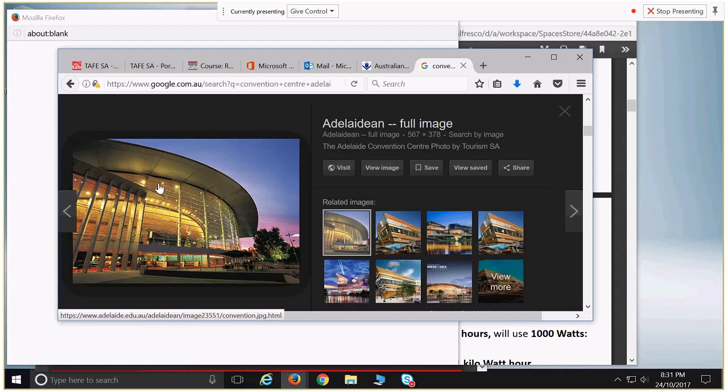So cable running up there, and cable running up there, and so in cross section, we've got our horizontal framing members and our glass coming off that, like that, and then cables with an adjustable nut, and then another horizontal framing member like that, adjustable nut like that.